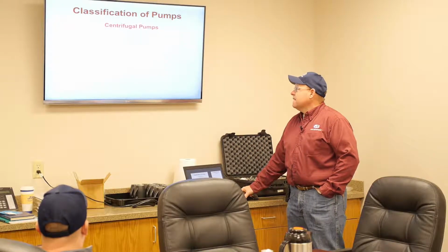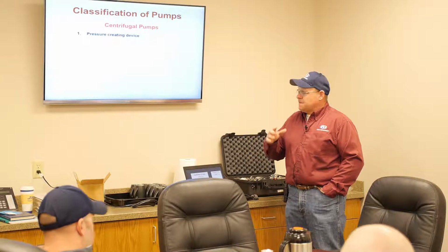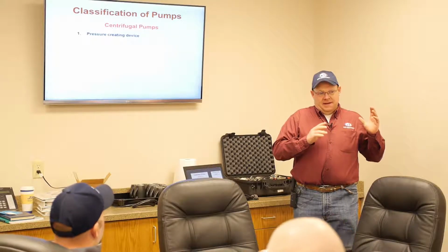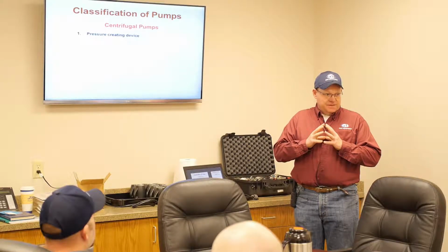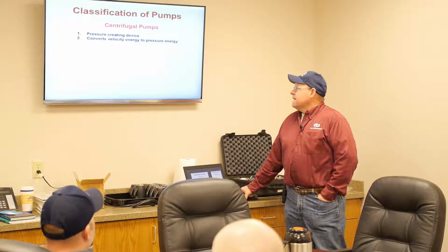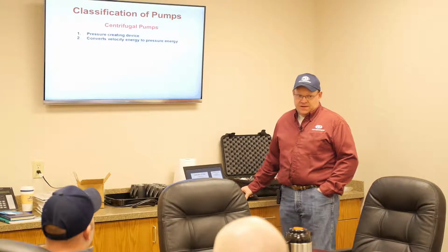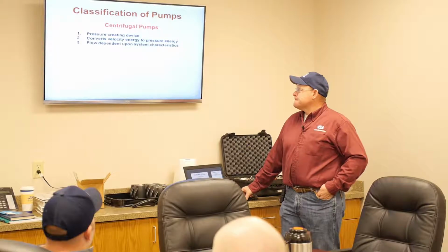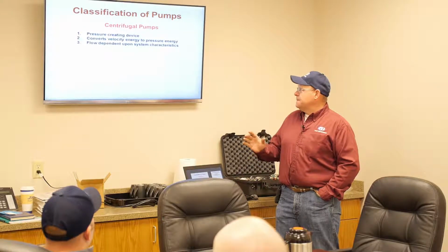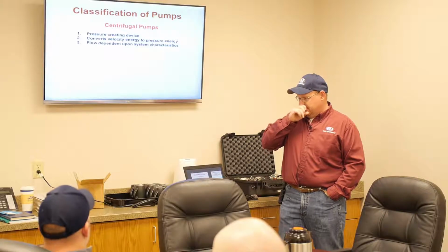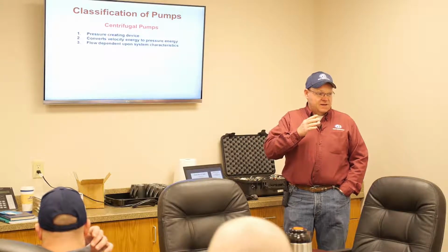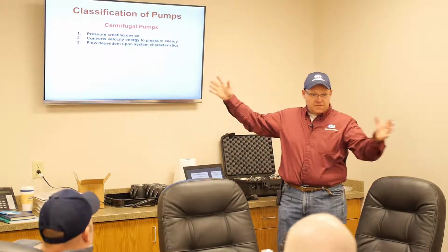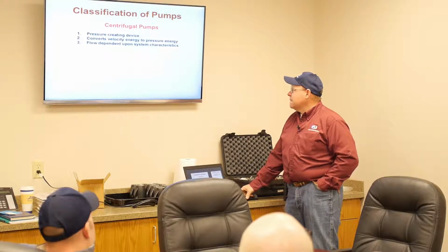Centrifugal pumps are a pressure creating device. And when we say that, just keep in mind that it's only going to do what pressure it can possibly provide. From that standpoint, it converts velocity energy to pressure energy. Is everybody kind of getting that? The faster you turn it, the more pressure you're going to get. The flow is only dependent upon the system characteristics. When we talk about the system, we're talking about the suction side, the discharge side, the tank, everything involved in that system, not just internally in the pump.